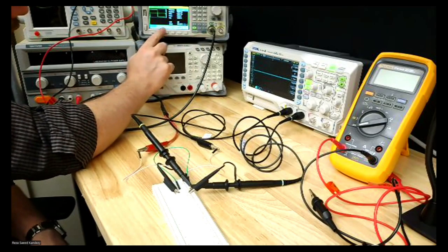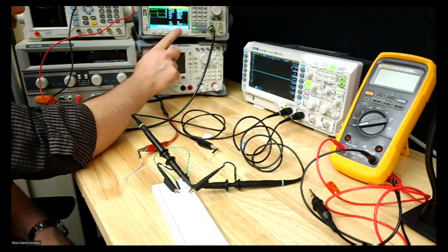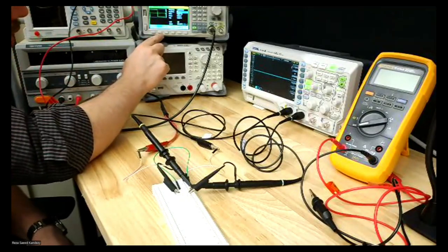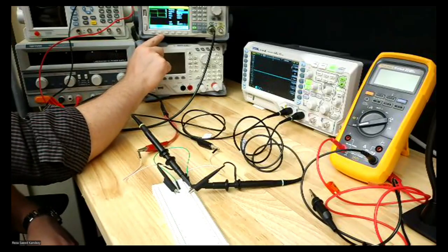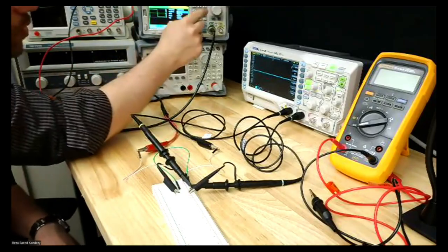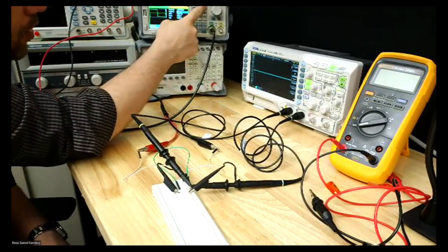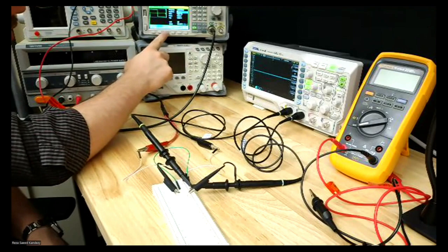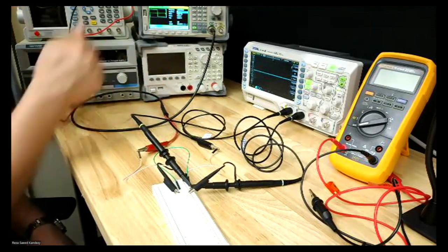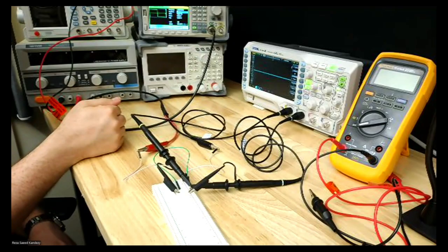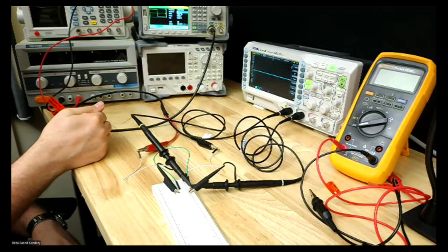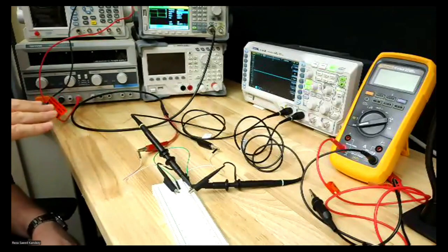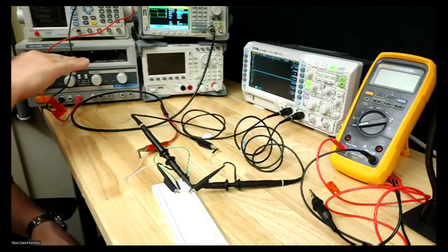Okay. Now I can change the frequency. I want 1 kilohertz. The default is 1 kilohertz, so I don't change it. The amplitude I want, based on the task, is 0 to 9 volts. So I put 9 volts peak. But when you put 0 to 9 for a step voltage, it's actually considered from minus 4.5 to plus 4.5, so it makes a symmetry over the 0 line.